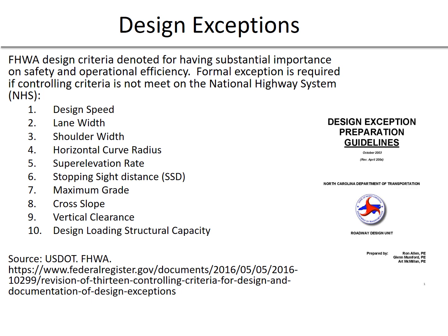The Federal Highway Administration expects documentation of design exceptions to describe all of the following: specific design criteria that will not be met, the existing roadway characteristics, the alternatives considered, comparison of the safety and operational performance of the roadway and other impacts such as right-of-way, community, environment, cost, and usability by all modes of transportation, the proposed mitigation measures, and compatibility with adjacent sections of roadway.